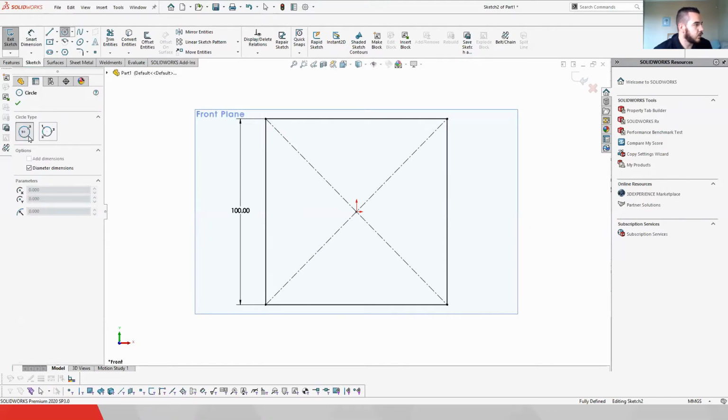Again, notice that you have the option. So it's either a 1 click or a 2 click or a 3 click. And very, very important, there's an option here that actually states, is the diameter the dimension or is it radius? Always make sure that you either use radius or diameter. It's very important. There's a massive difference between a 50 radius and a 50 diameter. You don't want to go and order a pipe that is a 50 radius if it was only a 50 diameter. Okay, lots of costing involved in that.